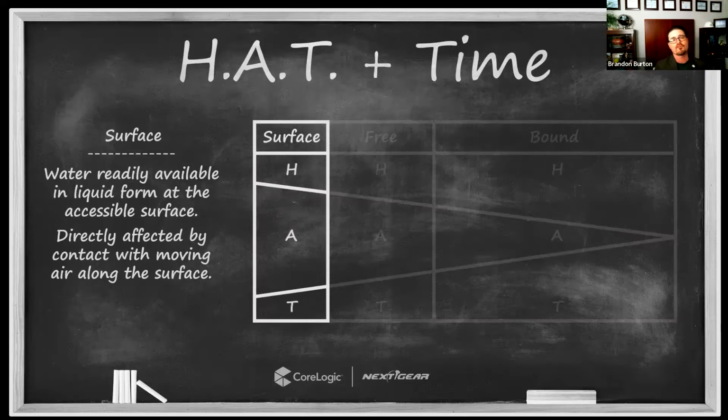Air movement is in direct contact with that surface water. And because air movement is in direct contact, notice here on this model how air movement fills the majority of my focus, the majority of my priority. Humidity is up at the top, temperature down at the bottom. We need to control them because we need to prevent damages elsewhere, but I don't need a 20% relative humidity to get surface water to readily evaporate. I just need good, rapid airflow right at the surface. Now, as surface water